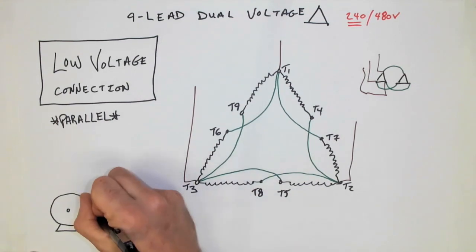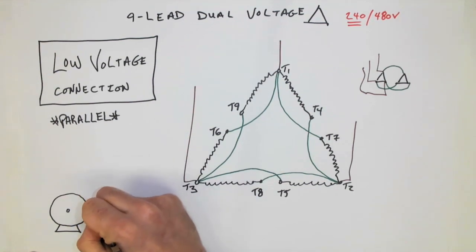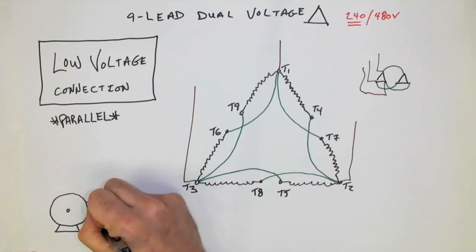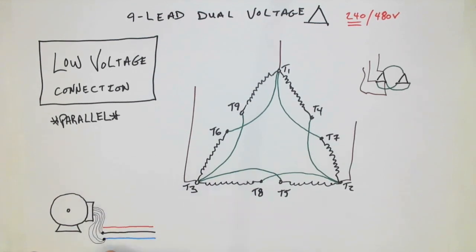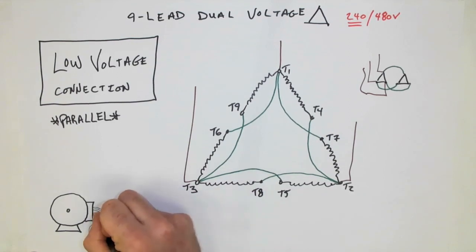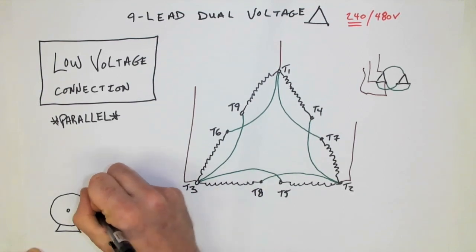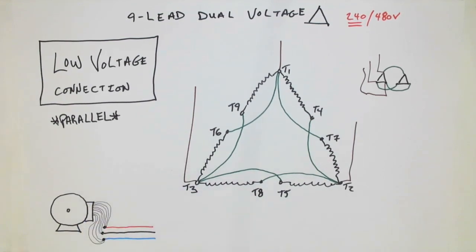We would then have the same thing again, 1, 2, and 3 connecting to our second line conductor. And finally, the third one here, 1, 2, and 3. So we'd have 3 wire nuts, and those wire nuts would contain all 9 of those conductors as well as the 3 line conductors that are going in.